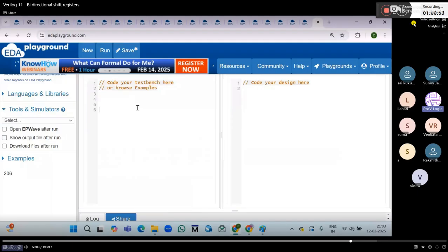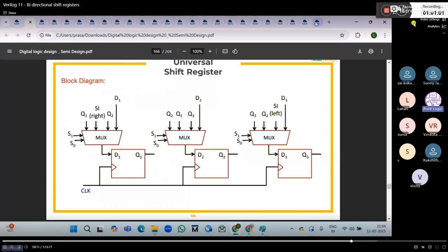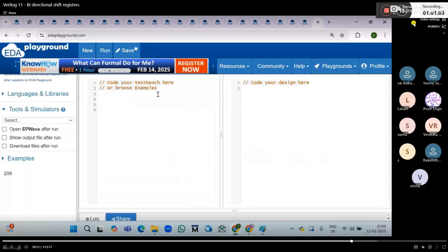Mode signal. First of all, we will consider the mode signal, or we can also call it a selection signal. I'm considering clock, selection signal, and also serial input signal, and parallel input, output Q. So declare all the inputs and outputs, always at the rate of posedge clock.